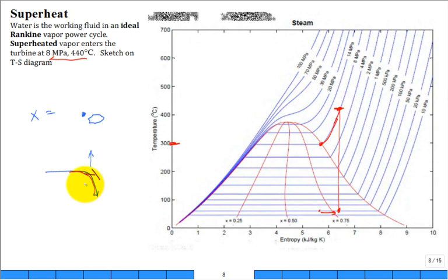Now you have something like a water droplet, pretty incompressible, pretty hard, impinging on metal. That's not good for the metal. And they'll get a little pressure pulse, and it's actually sometimes the popping back of the pressure wave that then spalls off and eats away or erodes, like cavitation. Who's taken fluid mechanics?